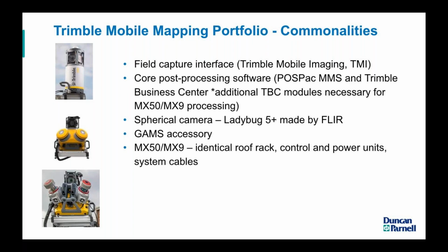In addition to that, the back office software tools start off the same. Use Applanix's POSPac MMS for trajectory processing. Use Trimble Business Center in the case of the MX7 to stitch the imagery together, and in the case of the 50 and 9, do that plus process your point cloud. So again, very similar workflows regardless of which piece of hardware you actually use.